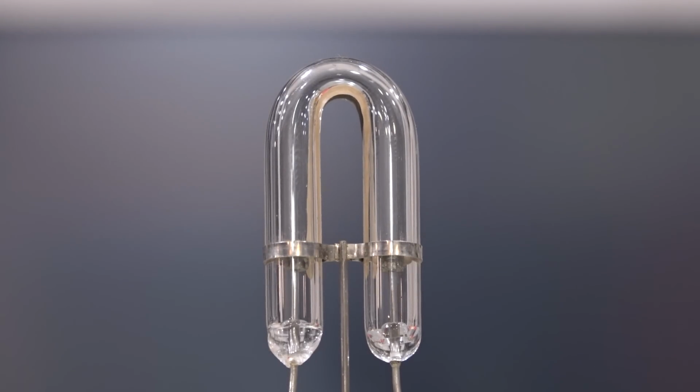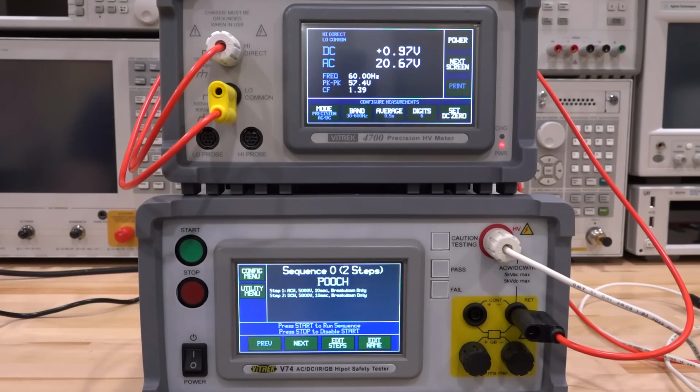Quite nice. Unfortunately, you would need a really, really high-speed camera to really see what's going on. Nonetheless, looks pretty neat. Now, probably one of the most common use cases for a high-voltage AC or DC power supply is a HiPot safety tester, where you apply a very strong electric field by applying a very large voltage to make sure that things don't actually break down.